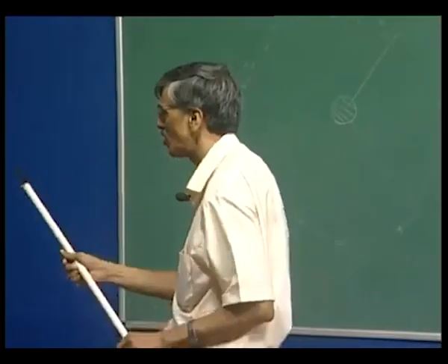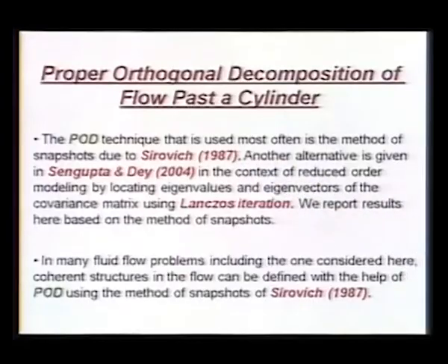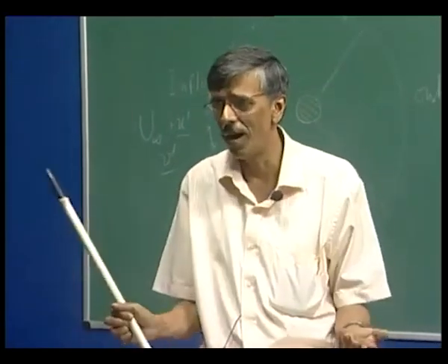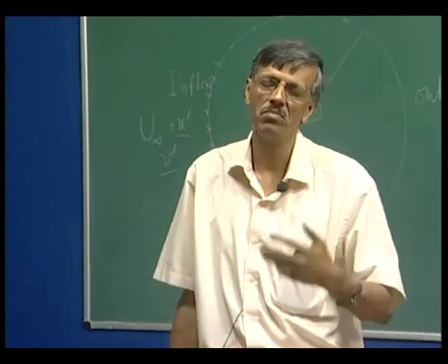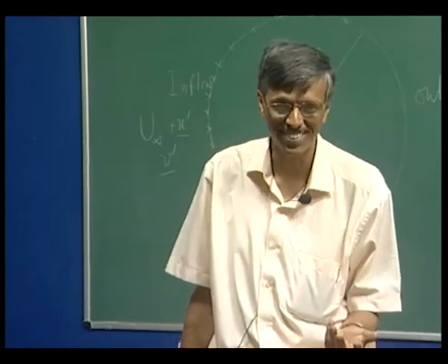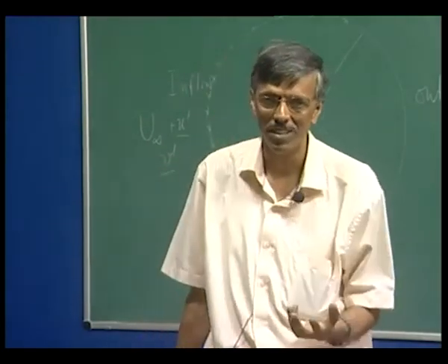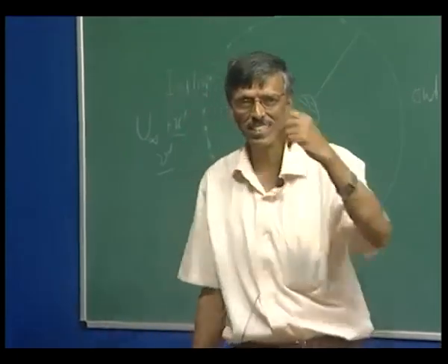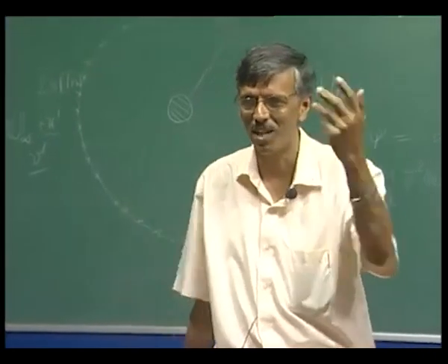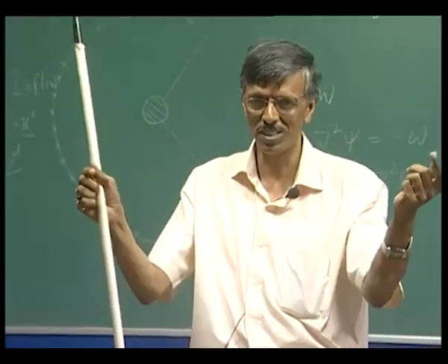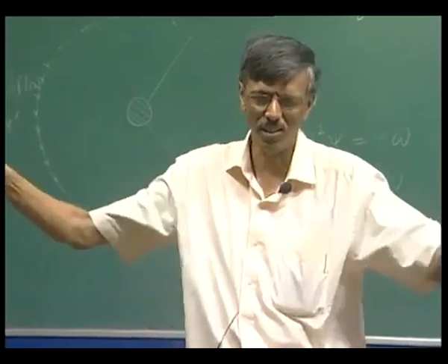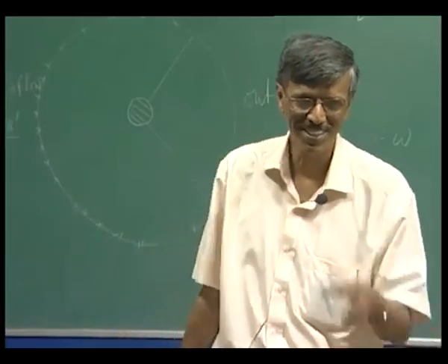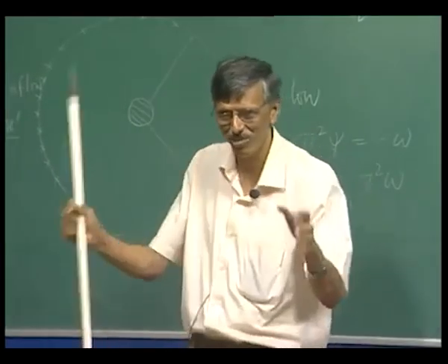So, the method of snapshots is so much more beneficial, because instead of talking about millions of points, here we are going to talk about fewer snapshots, a number of pictures in time. How many could that be? Yogesh will tell you that you take an interval delta t of the order of 0.01. So, in a unit interval you take 100 pictures, and then of course, sooner or later you reach the limit of your processor and you stop there.